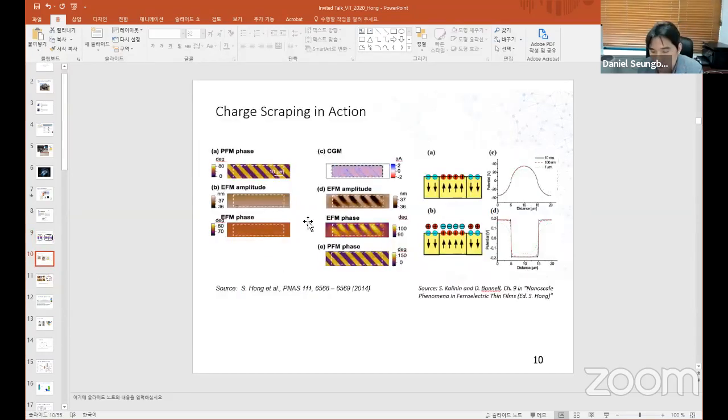So how do we prove it? Through materials imaging. We have three modes here: piezo response force microscopy, electrostatic force microscopy, and charge gradient microscopy. If you look into my book that I edited in 2004, when Sergei Kalinin was a graduate student with Professor Don Bonnell, he contributed a chapter where he calculated the surface potential variation of unscreened barium titanate, where the domain size is about 10 microns, and then fully screened barium titanate, and how that contributes to the surface potential variation when we measure with an AFM tip. You can see that the surface potential difference between up and down domains when unscreened is about 80 volts, which is large, but if it is fully screened, it's less than 400 millivolts. So you can see orders of magnitude change just by having screening charge on top of your ferroelectric domains.